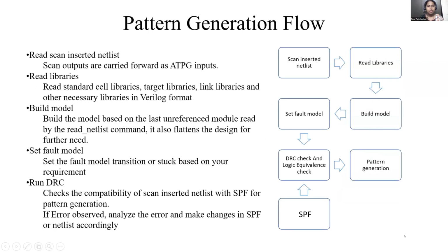Okay. Now, how are the patterns generated? First, we have the scan-inserted netlist, that is, our netlist in which the DFT configuration has been put. Then the tool we use for pattern generation is TetraMAX. So this is the flow for that tool. The flow for every tool is more or less the same, but steps may vary a little with the tool.